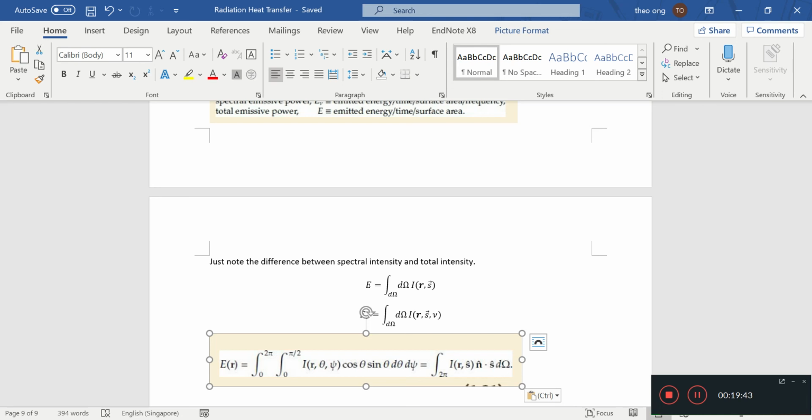Now that we are talking about solid angles and intensity, we can start defining absorptivity and emissivity. Now we can describe the intensity of a body of any kind, and we can relate that to the black body. If we relate that to the black body as a reference point, we can talk about emissivity and absorptivity.